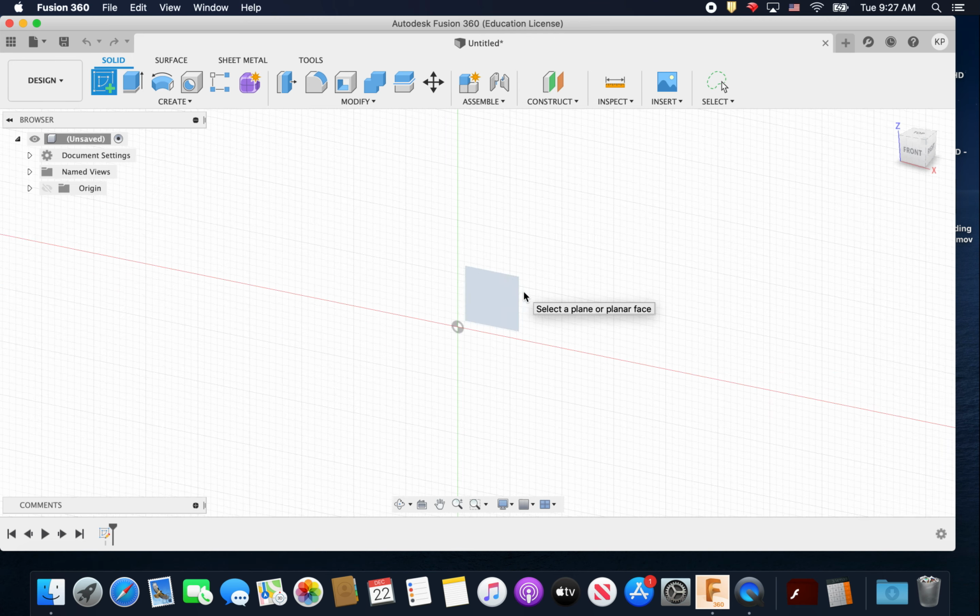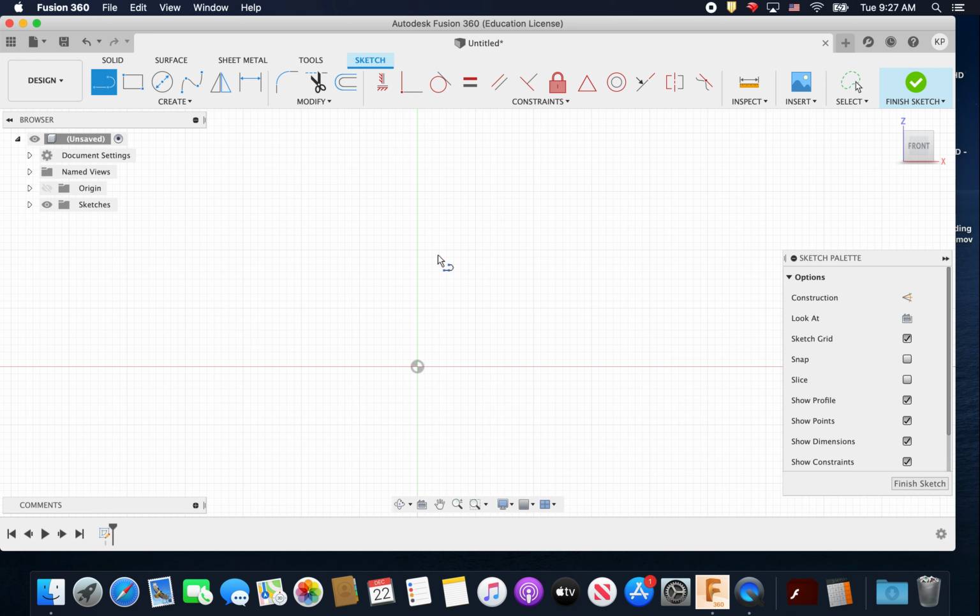So I'm going to select a sketch plane, I'm going to do L for line, and I'm going to just draw that side L shape of that drawing that I showed you. Make sure you get the alignment and back down. Okay, so hit the escape key and that'll get you out of your tool, and we're going to start by dimensioning a few things first.